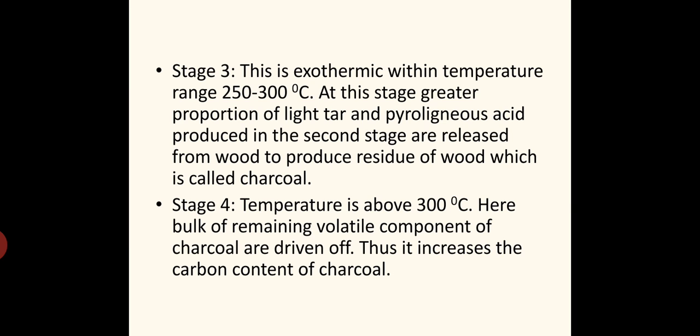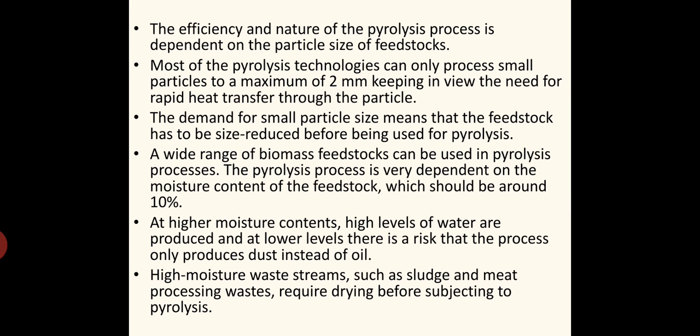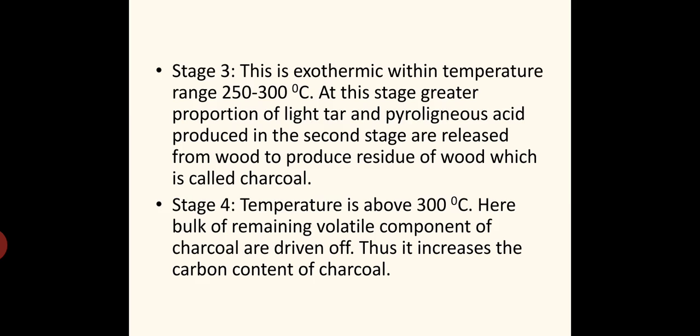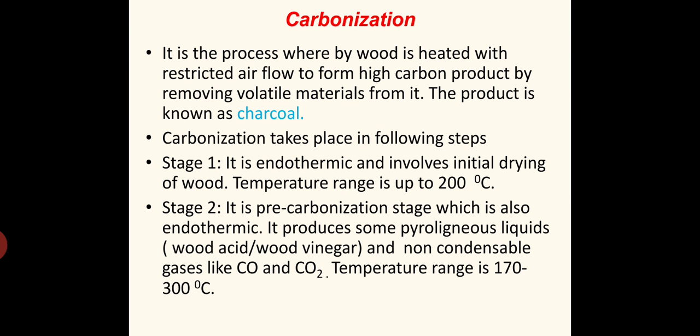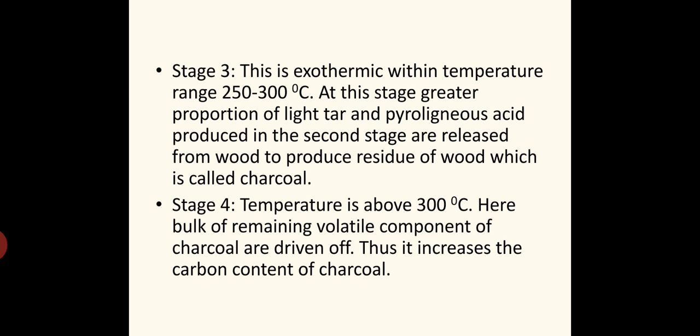So finally, what we obtain by carbonization is pure charcoal. Charcoal is nothing but the high carbon content solid produced from the wood. That's all. The remaining products are removed. Non-combustible CO and CO2 are removed initially. In the first stage, volatile materials are removed, and in the third stage, along with charcoal, we are obtaining a liquid fuel also, known as wood vinegar or wood acid, which is brown in color and liquid in phase.